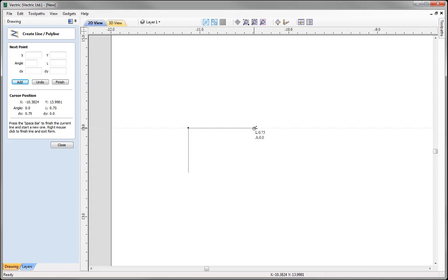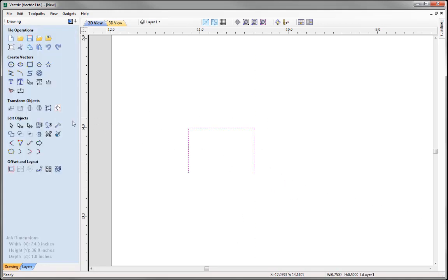I'm just going to zoom in a little bit so I can get the length there of 3/4 of an inch. I'm going to bring that back down so we've got a length of 1/2 inch there, and then we can click that in place, and just to make sure that I know that we're in line with our original point, I can see that represented by this line here. Okay, as we're creating cross sections, they need to be open shapes, so we're going to leave it at that. So we're going to right click to come out there, then we're going to edit the shape using node edit.